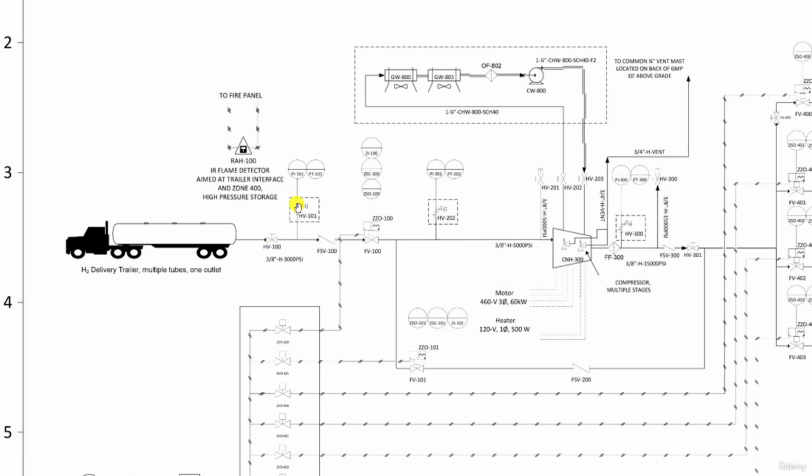Now, between these two valves, you have a process connection to a pressure indicator, PI101, and to a pressure transmitter, PT101. This is to measure the pressure of the hydrogen line. Notice here that these pressure instruments are not involved in any control loop or safety loop. So basically here, it is just to monitor the pressure of the line. The P&ID symbols for these pressure instruments have a divider or a horizontal line running across the center of the circles, which means that they are board mounted.